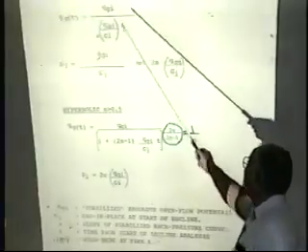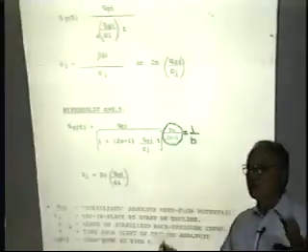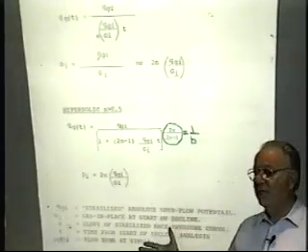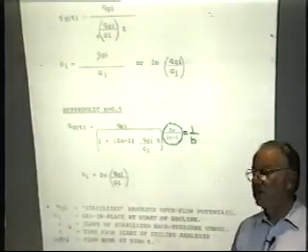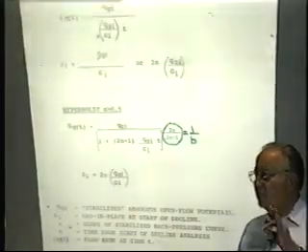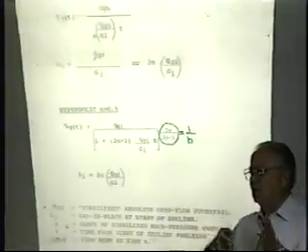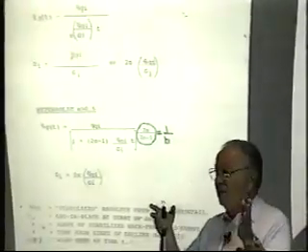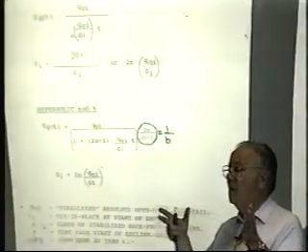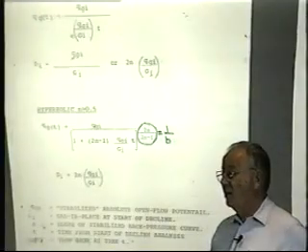What we have here is an exponential or back pressure curve with a slope of 0.5. So if I have performance data on a gas well and it's got a slope of 0.5, I can tell you the B value should be close to exponential. Normally what's going to make the B value 0.5, particularly at the wellhead, I can take the P over Z or the bottom hole shut-in pressure and take it to the wellhead conditions, and I have a wellhead curve and a PC, and that's where I'm going to deliver the gas. So it's the slope of the wellhead deliverability curve that I'm interested in for setting the value of B.